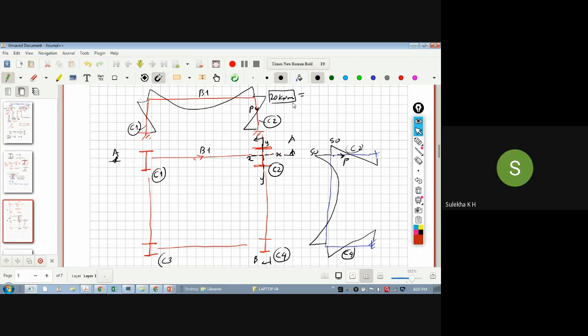Myy. Myy, because this axis is y and about that axis this moment is there. So this is your Myy. We can call it a minor moment also because it is about the minor axis. And then what is this 50 value? It is like this, about x axis. So this is Mxx, which is the major moment because it is about the major axis. You know major axis, minor axis. Getting this? Is everyone understanding?